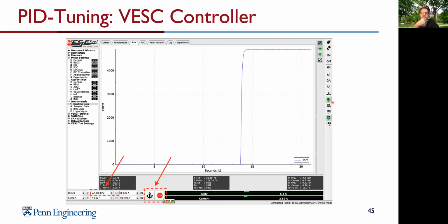So to create a step response for the motor here, you can set a target RPM. We create that here. A target RPM, you can choose between 2000 and 10,000 RPM. Then you click the button next to the box to start the motor, which you can see here. And be careful about that, because the motor will spin afterwards. So you make sure that the wheels of your vehicle are clear from objects and it is not located on the ground. Click the enter or the stop button right next to it. This is for stopping the system, and this for applying the step response.